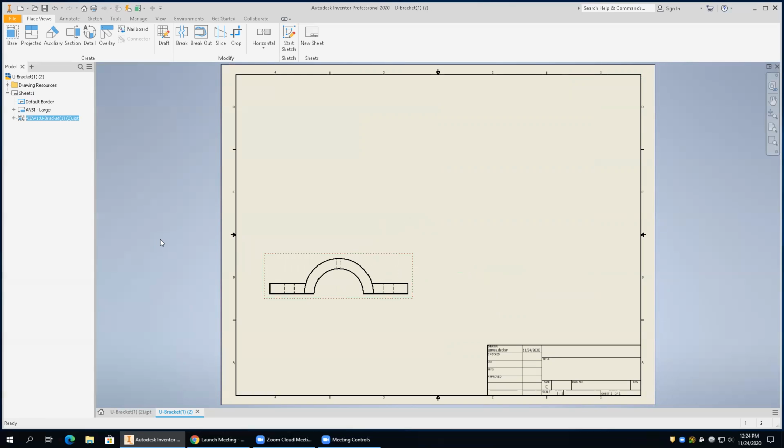Okay. So if you're not seeing hidden lines, you have hidden lines removed. If it's shaded like mine was, then you got that shade on. Okay. So we got those 3 views. Is everybody good? Since this is my base view, then I can now produce what are called projected views, tops, sides, bottoms. So we're going to go to a projected view.